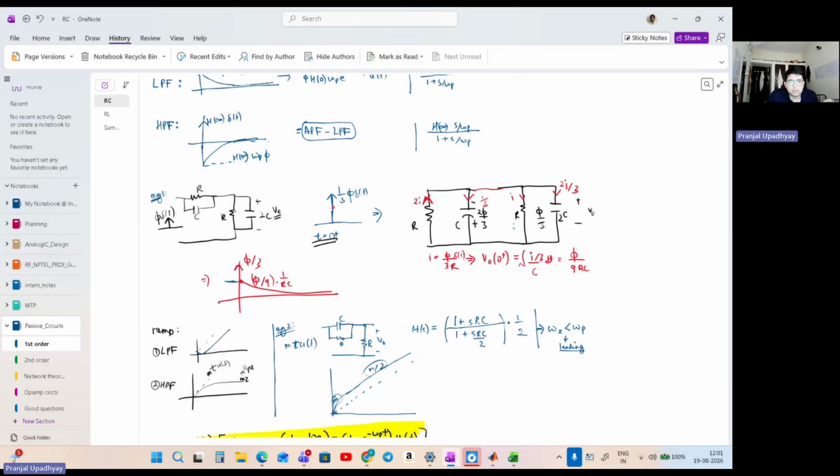So now let us try to deal with this particular question. Okay. So now what will happen is that when we feed the impulse to the circuit, at that sudden point of time, only a portion of that impulse will appear over here, which is 1 by 3 times that impulse, right? As I said, and this will happen at t equals to 0 time, right?